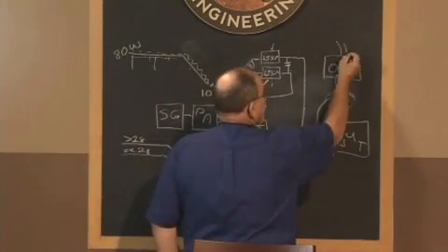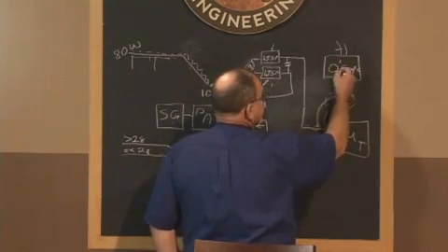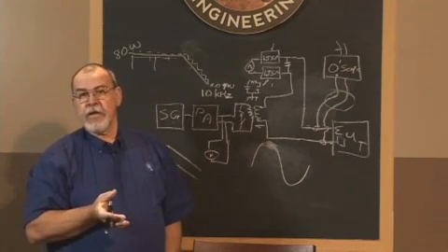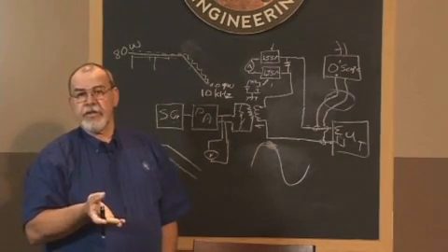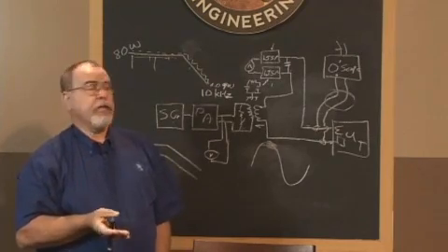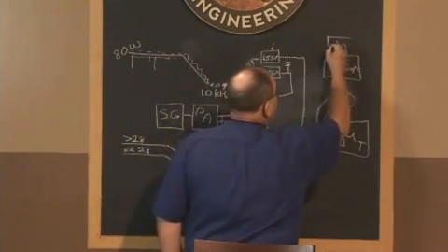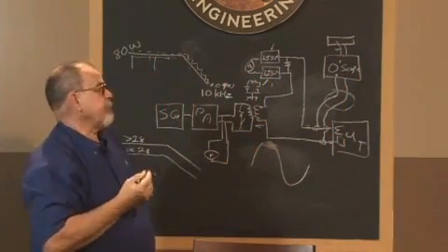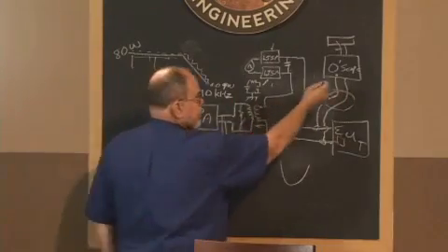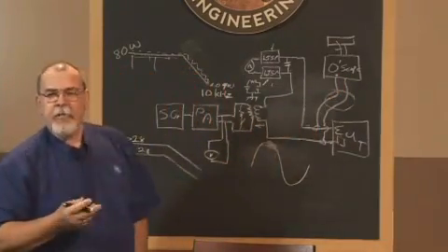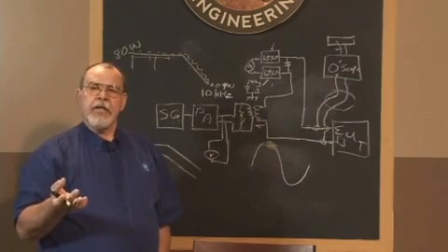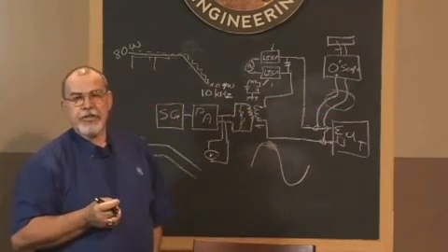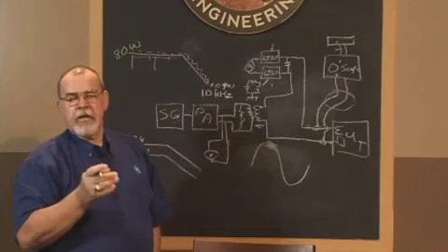my oscilloscope primary power is grounded, so now I've shorted this ground to that. What happens is my probe flashes in a ball of flame, lasts a few milliseconds, the flame's about 7 inches, and your probe burned out. Okay? So we have to put an isolation transformer here to prevent grounding of the oscilloscope to the primary power. Okay? So when we do that, we make this oscilloscope body a live circuit. Well, most of our oscilloscopes have a plastic body, except for that little BNC connector that we use to connect the probe to. So if you touch that or the ground pin on this oscilloscope, you're live.